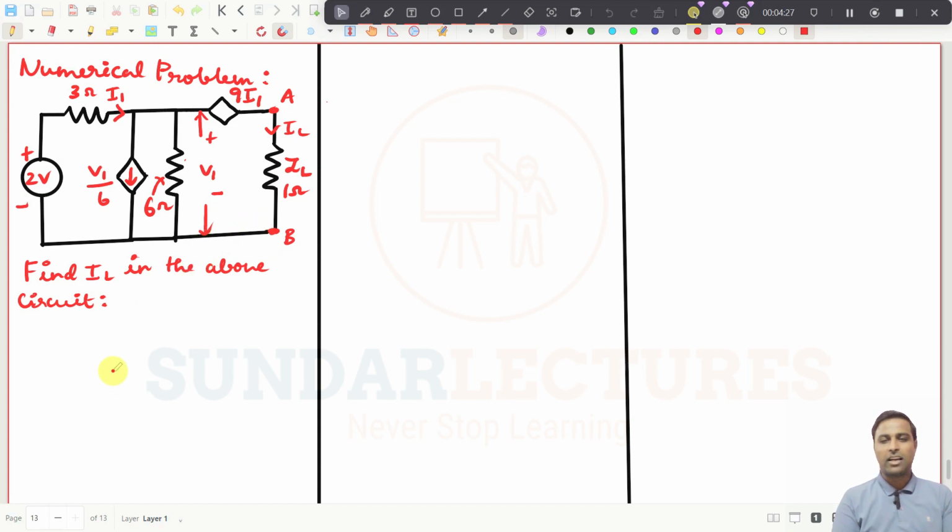We will take Thevenin's theorem to solve this problem now. Let us assume that we are going to solve this problem by Thevenin's theorem. Since there are dependent sources available, to find the Thevenin's impedance we cannot go by the conventional method of short circuiting and open circuiting the sources. It is not at all possible. Anyhow, we will solve this problem by Thevenin's theorem.